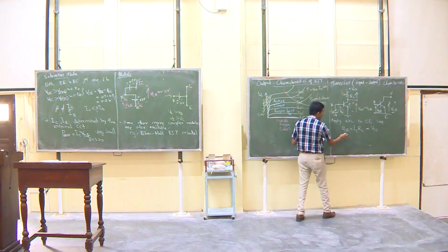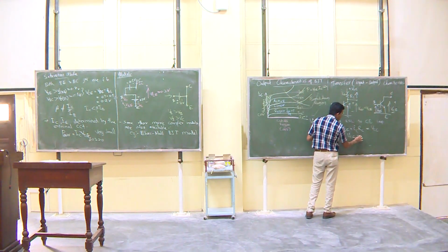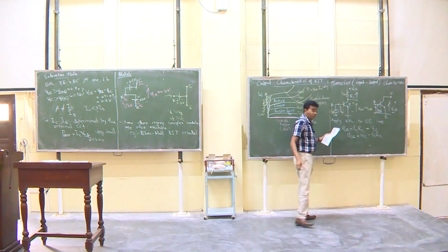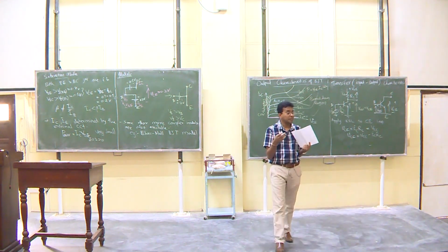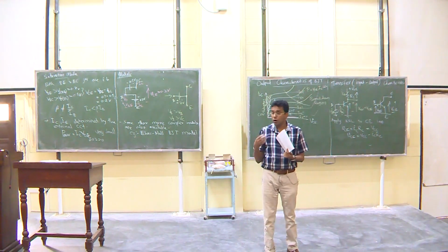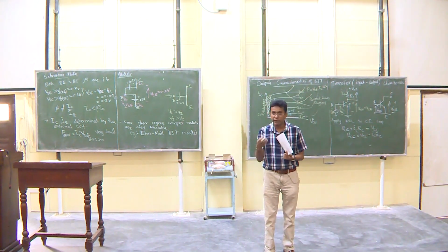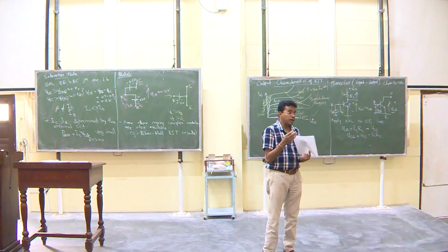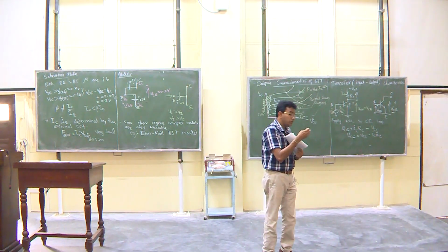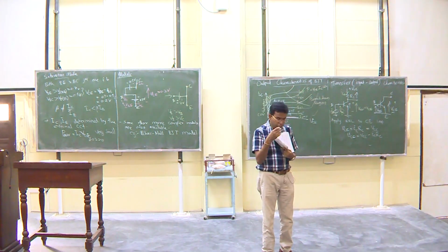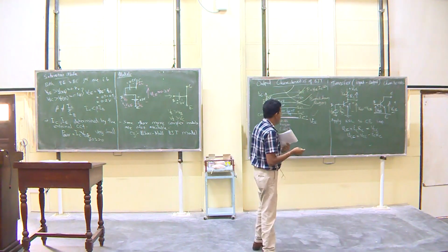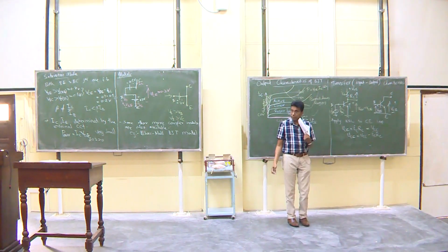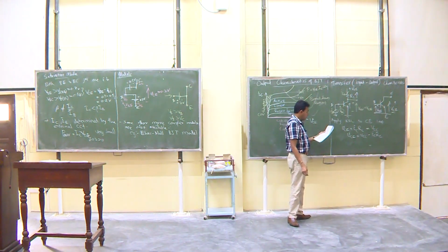So, this gives me VCE is equal to VCC minus IC RC. Now, what I am interested in is not a relationship between IC and VCE, that is actually the output characteristics of the transistor. What I am interested in is VCE and VBE, the input voltage. So, then I need to replace this IC with some function of VBE, right. So, that is my goal.